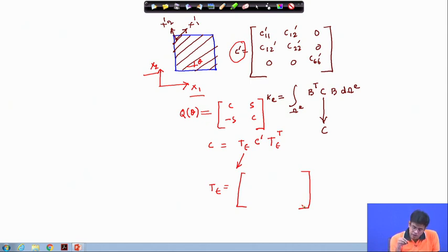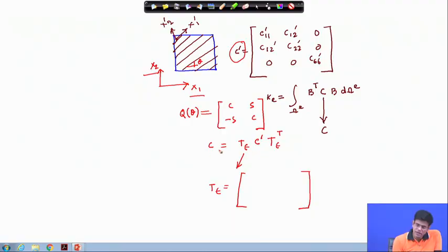So this is very useful to solve this, and we need to transform the material property to the structural axis. This is why it is important. This C is along x1 x2, and you will see if you do it on your own with MATLAB or any other software, if you do these multiplications, this is an orthotropic material with 4 independent constants, but this C may not look like this form.